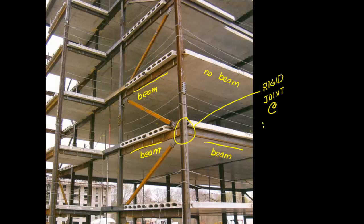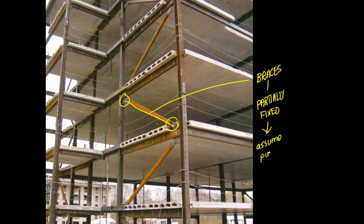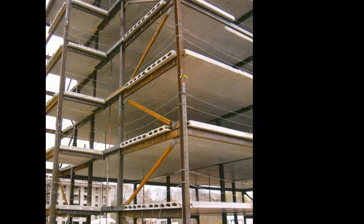The beams are attached to columns with rigid joints. This is a braced frame combined with a moment-resisting frame. The joints at the brace ends actually are partially rigid, but for analysis we assume that they are pinned. The column has a splice with a rigid connection. A single full-length column would be too long to ship on a truck, so 2 separate lengths are spliced together in the building. Now let's do an examination of the floor loads.